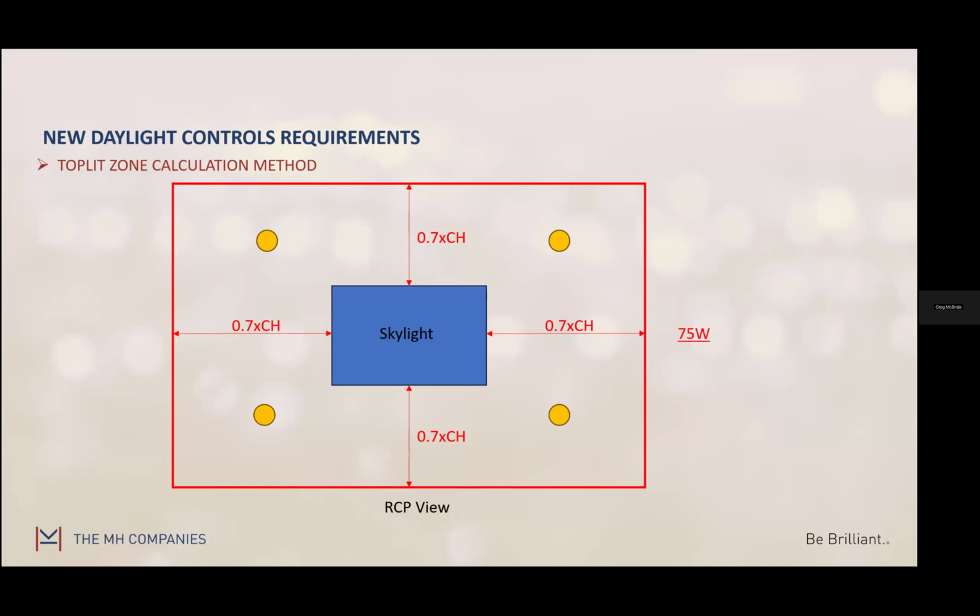Is theatrical lighting included toward daylighting zones wattage levels? So no, I would say theatrical lighting, that's especially lighting basically. So that would not count toward it, though your house lights may have to dim. In most cases, I haven't really seen too many theaters or applications where you have theatrical lighting that would have windows, typically. Usually those are enclosed spaces, but I suppose you'll see them in gymnasiums sometimes, where they use that space for multiple applications. But no, those do not have to be daylight harvested.